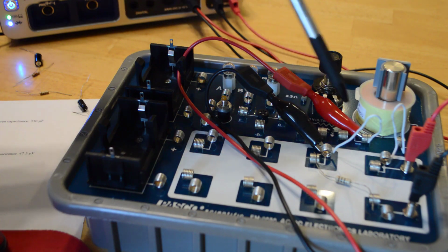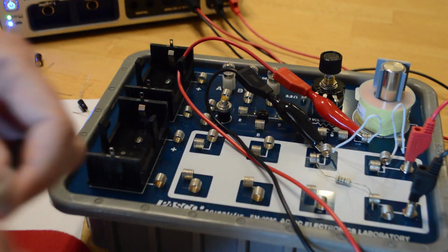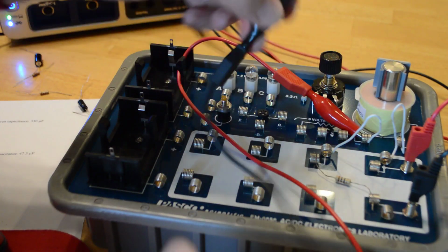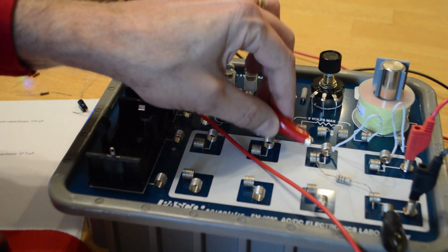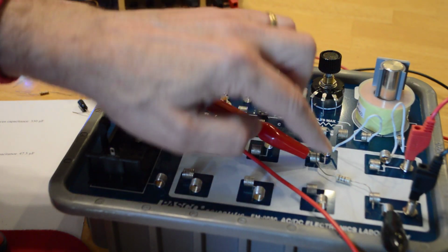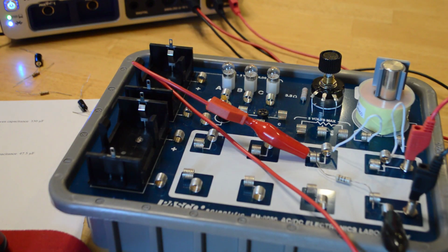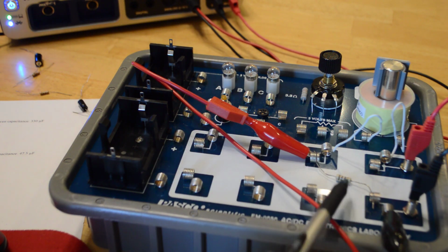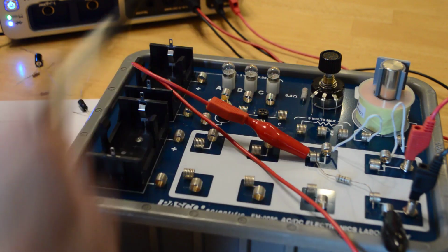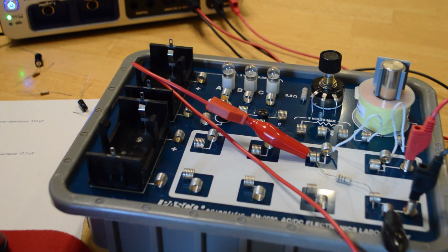And so here I have measuring, whoops, I got this in the wrong spot. I want to measure the voltage across the resistor, so that's going to go between here and here, and now I can measure the voltage across the resistor. But first of all, in my simple series circuit, this is not the only resistance. The coil will actually have some resistance as well. So I want to measure the complete resistance of my circuit.